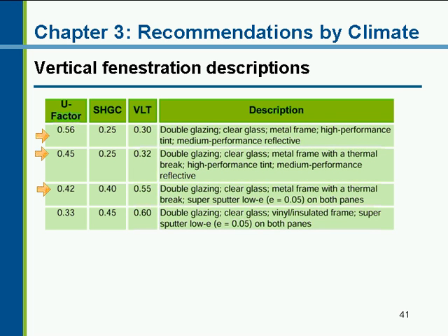So there are several types of low emissivity coatings. There are pyrolytic, also called hard coats, that are actually baked onto the glass when the glass is made. And then there are the soft coats, the sputter coats that are put on by a vacuum deposition process later on. The sputter coats don't hold up as well to the outside environment, so they're always installed on the inside of glass. The pyrolytic, the hard coats, they're the type of things that people can use in storm windows.